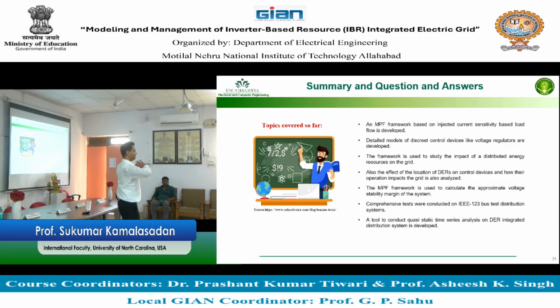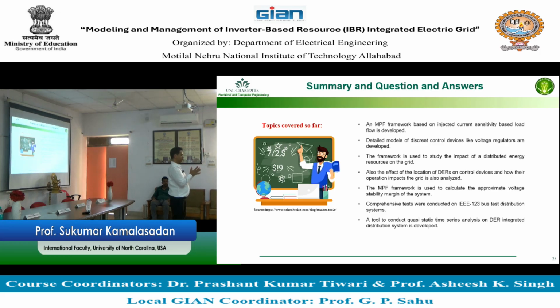So, having said that, I hope you got a glimpse. Quasi steady state time series power flow means, along with the power flow, including devices that change in a step change between times. So you model the device and include that in the quasi steady state power flow, which represents the real system when the input changes.